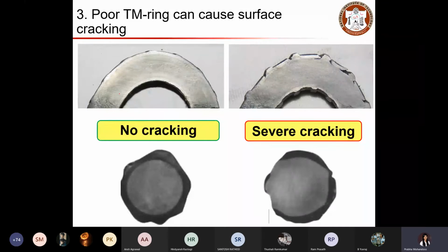Whereas when you have some deformations on the surface, when the outer ring is not formed properly and there is a discontinuity in the surface, then when you bend, you will start observing such shear cracking. Why? Because this portion is not strong. You do not have a hardened region here which can withstand the load while you bend the rebar. That is why you observe a lot of cracking on the surface when you do not have proper ring formation, like in this case. So this will affect the performance significantly when it is being used in construction.